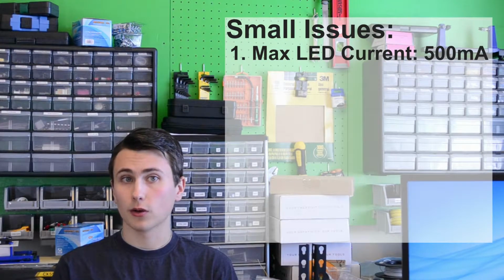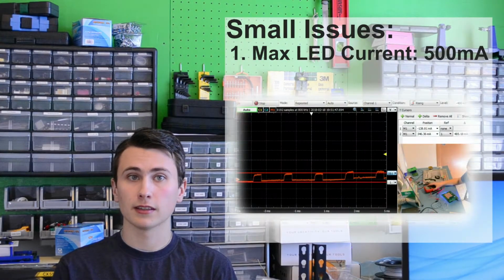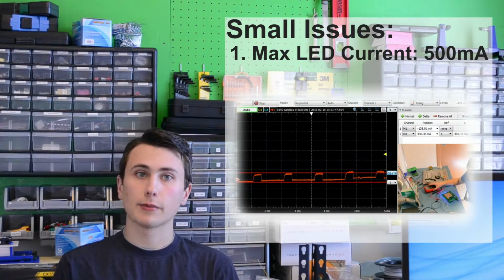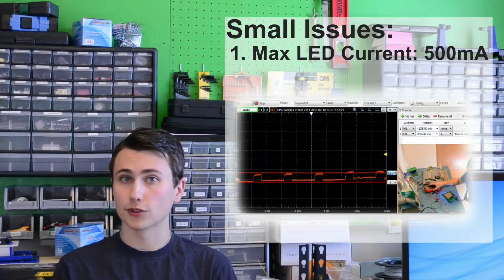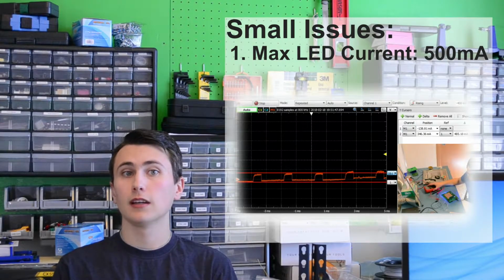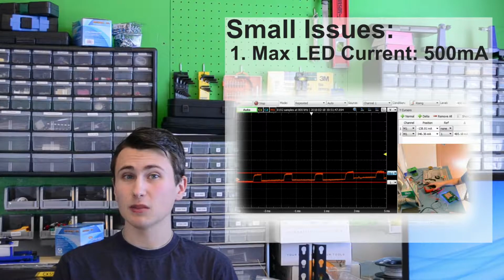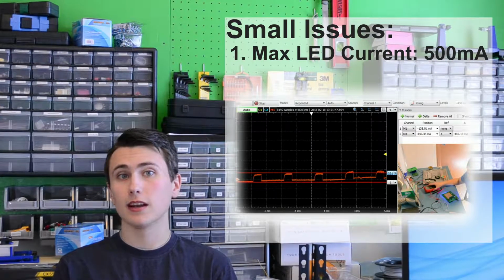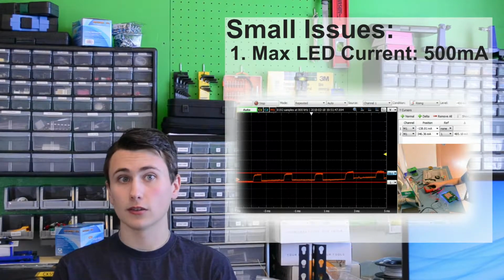Since we learned that the current regulators are pulse width modulating the peak current of 500 milliamps, or whatever it's set to, instead of dynamically changing the steady state set point as a percentage of that maximum, this means that some of the LEDs were being exposed to peak currents higher than their maximum rating. This was not the design intent, and that's not good.